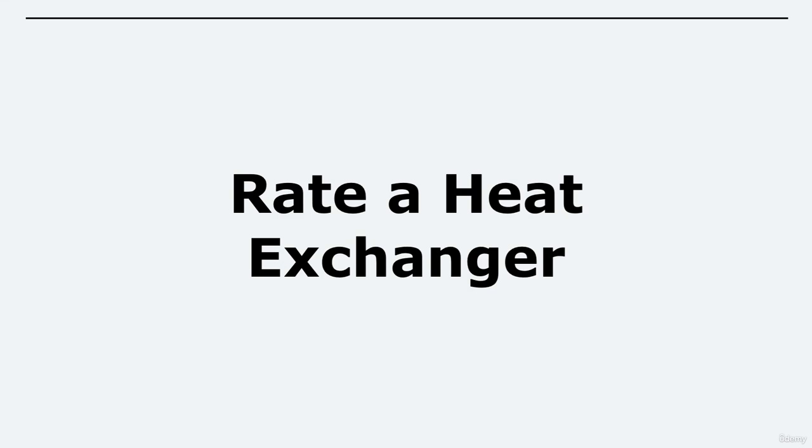In this video, you will incorporate HYSYS-based heat exchanger rating calculations into an existing heat exchanger model. You will also follow the workflow to use Aspen Shell and Tube Exchanger via Aspen Exchanger Design and Rating to rigorously design and simulate a shell and tube heat exchanger.